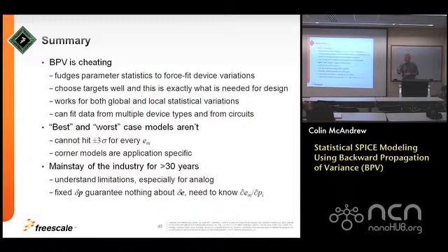They will have input into the technology saying that if you don't get the matching below this level or if the variability of this is too big, we're not going to be able to use the process. But it doesn't really factor into how the model's used. That data flow is manufacturing to specifications, which involves some discussions and thought as well. Then that flows into the models and that flows into the circuit simulations. So your goal is basically to tell the designers, given the variations that the manufacturing line has given us, this is the impact on the circuit.